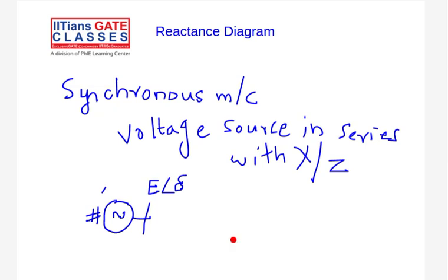So there is also one more aspect when it comes to a synchronous generator. You know that it is a three-phase connection, right? Any three-phase connection can have two possibilities: either it is star connected or it is delta connected, right? Usually for generators, we always prefer star connection because of the presence of the neutral, so that we can extract each phase separately, right?